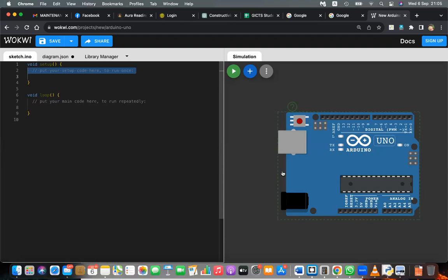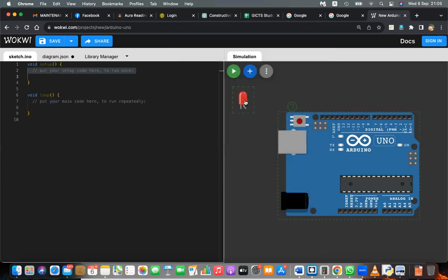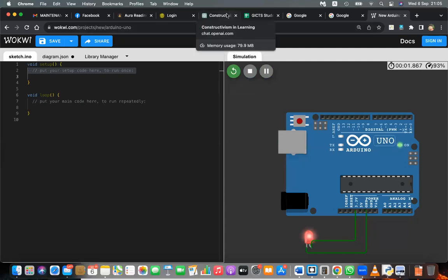Okay, very first thing, you can test this with an LED. You can get an LED and just connect the LED to the 3.3 volt pin, and the other pin to the ground pin, and check whether this is working. This is a very simple activity. Connect the other pin to ground and check whether this is working when you play this. Simplest activity, because we are using existing power. Okay, please do it now.